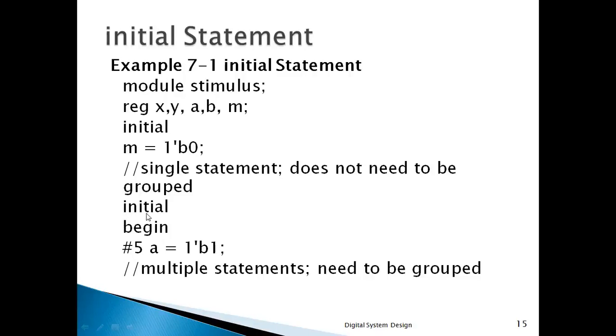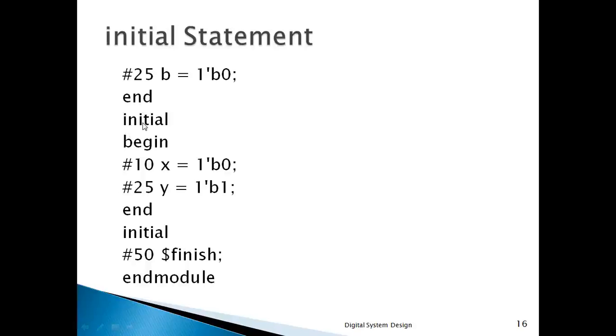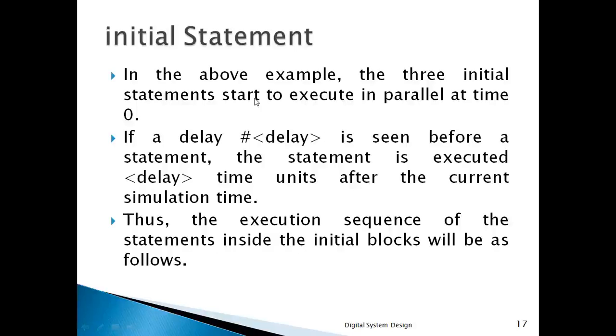Here you see that this initial statement, these all will start at time 0. This also starts at time 0, and these 3 initial statements are executed in parallel at time 0 and the delay specified. The statement is executed delay time units after the current simulation time.